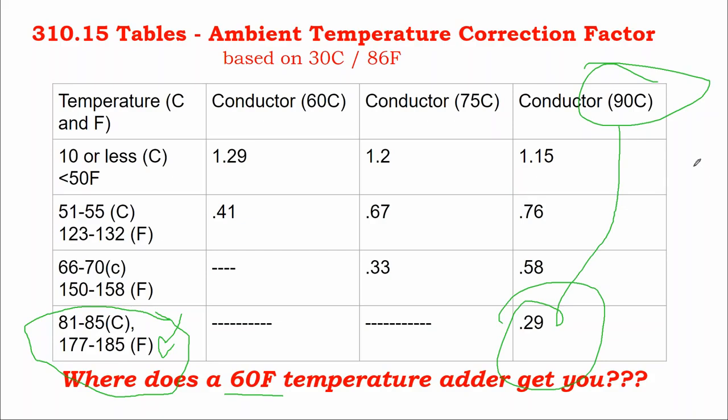But actually, this isn't so bad, because it's not just ampacity sizing in cables. It's the friction of the electrons as they're flowing through the cable itself that results in losses called voltage drop. So you often upsize solar cables anyways because of voltage drop.